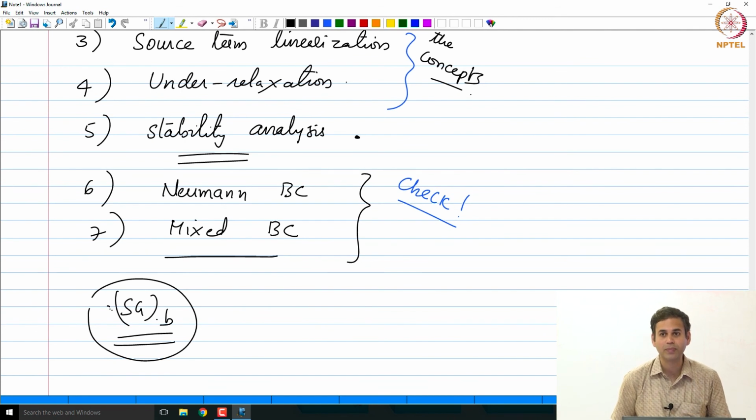Suppose we have a domain that has a plane with the fluxes entering normal to the plane. In that case, suppose the domain is divided into an unstructured mesh. So that plane will have many cells whose boundary is on the plane. And each cell is unstructured, so each E zeta will be in different directions. So in that case, the flux is definitely along the normal, but E zeta is different, so you can't assume. Yeah, true, that is true. It depends on the cell.